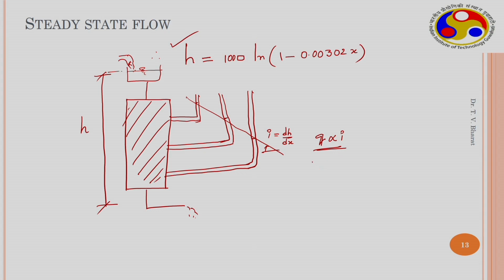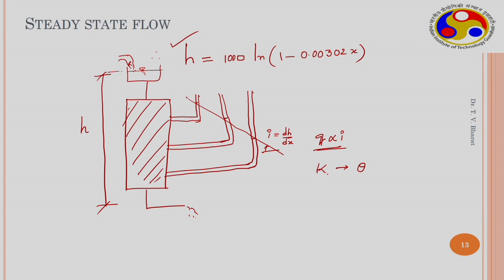So in this particular case, you can estimate the hydraulic gradient, and corresponding moisture content can be determined by a destructive technique. You can take a soil sample and measure its weight, then put it in an oven, and again measure the weight, and you obtain the gravimetric water content. Knowing the density, you can estimate the volumetric water content. So there is one hydraulic conductivity which is estimated corresponding to a given theta. By varying the head, you can maintain different volumetric water contents, and you will get different values of K. So this way you can obtain hydraulic conductivities which are less than the saturated hydraulic conductivity.